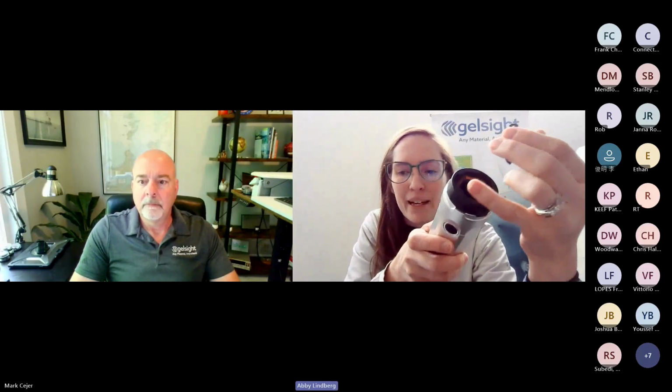I'll turn the light off here so we don't have to look at that while I take the gel out of it. So we have the camera, the lens, and the illumination system. When I click this button, I'm actually taking a series of images, 6 images here, one with each one of these banks of LEDs illuminated. We use those 6 images with the 6 different lighting orientations to basically calculate slope based on pixel intensity. That's what's giving us our 3D data.